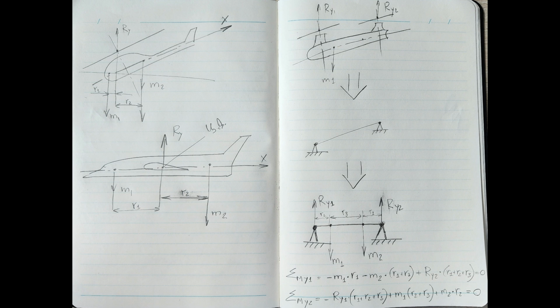In the case of a quadcopter, the suspension scheme of the device may, in first approximation, be simplified to a beam. A beam in this case is a fuselage or body, suspended on two hinged supports. Each support is a projection of electric motors located on different sides of the plane of symmetry of the quadcopter.